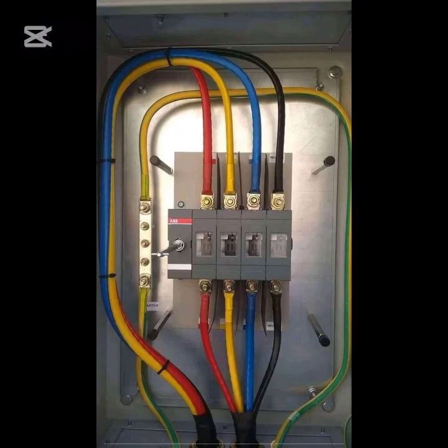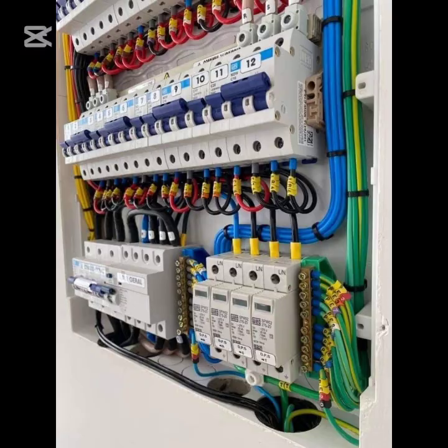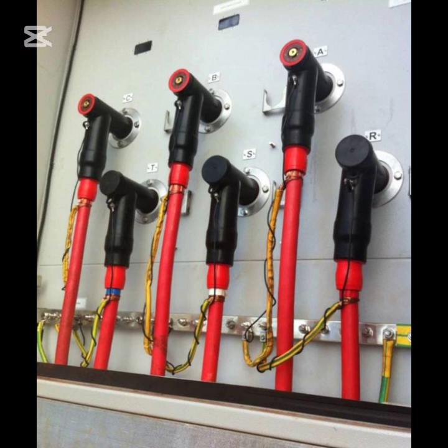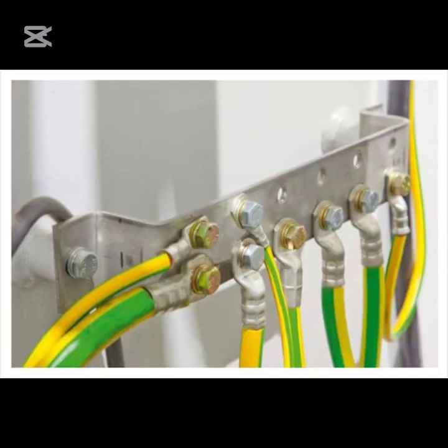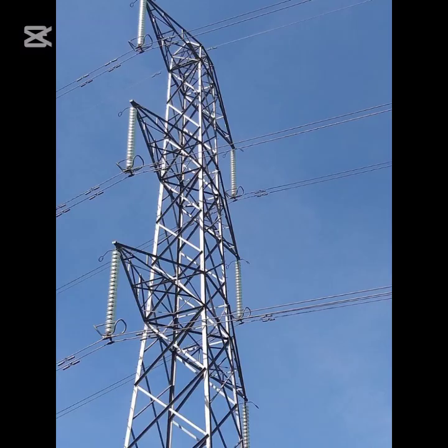1. Stranded wire offers greater flexibility when in use. 2. It is easier to control through narrow routes. 3. Stranded wire reduces heating and allows safer current flow. 4. It is suitable for crimp connections and patch cords. 5. Stranded wire offers a lower skin effect, especially for longer distances with high voltage transmission lines.